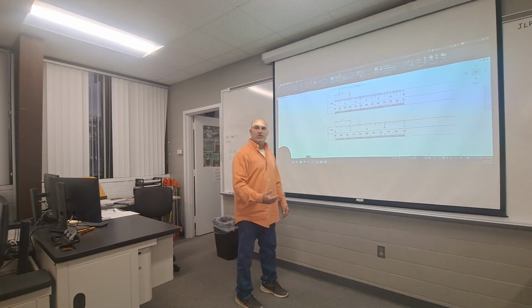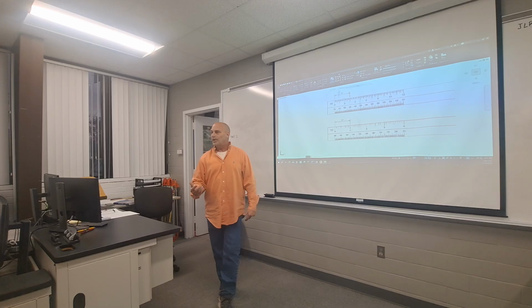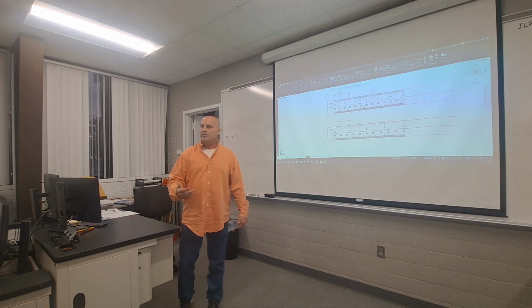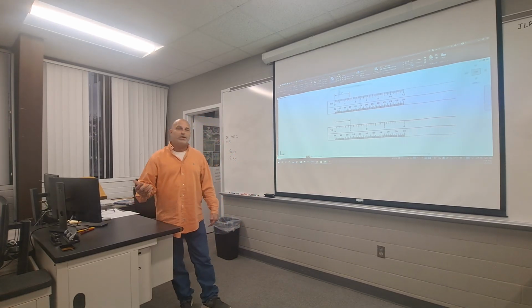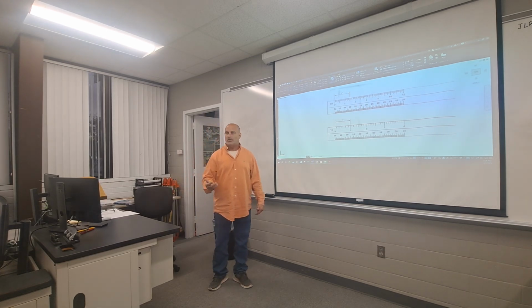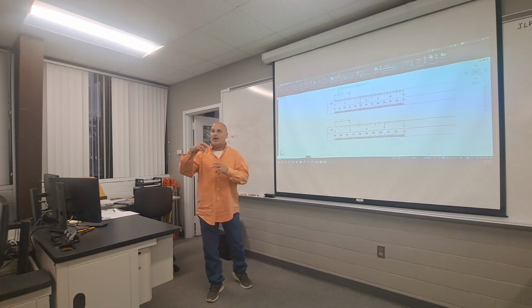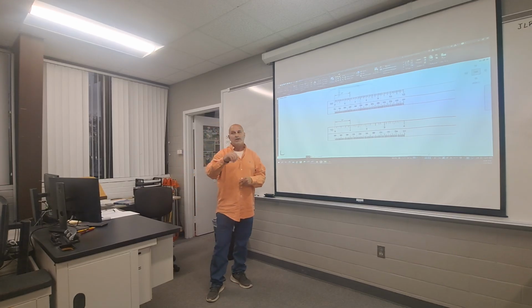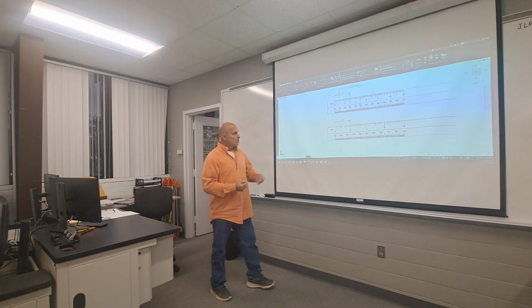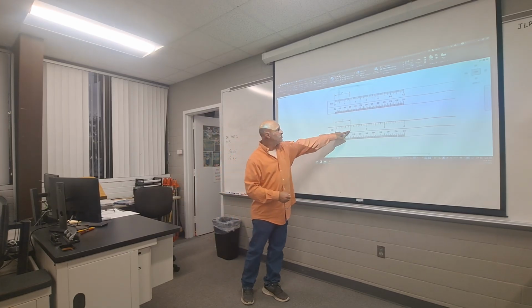That's the purpose of the scales, is to be able to get out and reference that drawing. We use them quite frequently where we're at, because something I told y'all last week: in the civil world, we don't show a lot of dimensions, if any, on our drawings. Actual dimensions with extension lines, dimension line, arrowheads, and the text above it. That's not how we notate drawings in the civil world. So we're not gonna be able to look up there and just find that measurement. So we're gonna go to it with the scale.